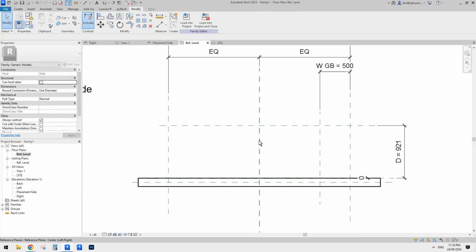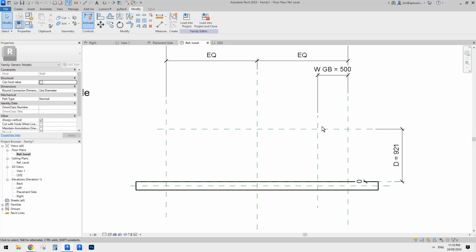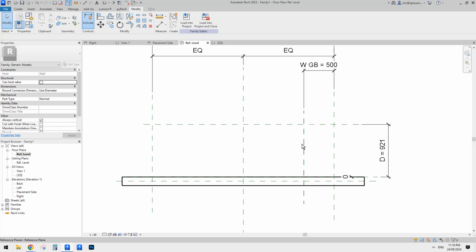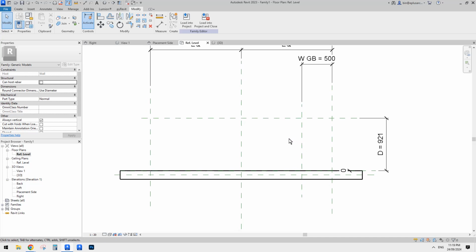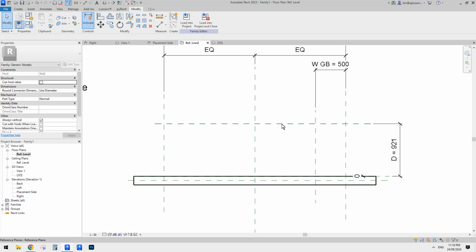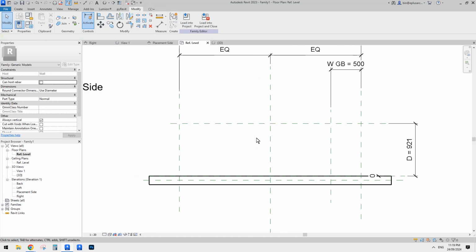What else do we need? We can do the railing with just a sweep, so we don't need an extra reference plane. For the garden bed, we can probably also do a sweep, so we can avoid having more reference planes as well. We can just use a dimension in the profile. So this is some planning: try to avoid having too many reference planes.